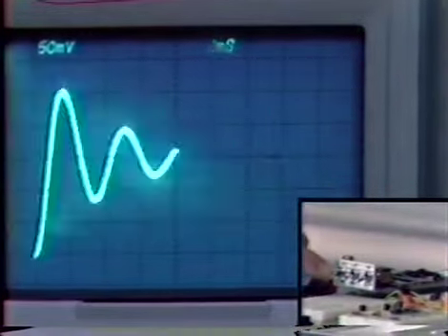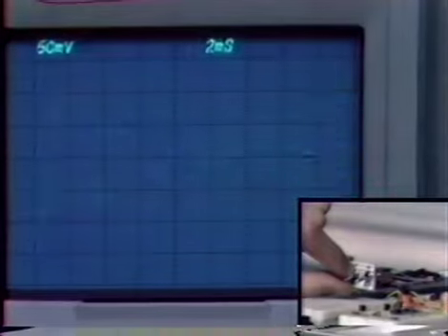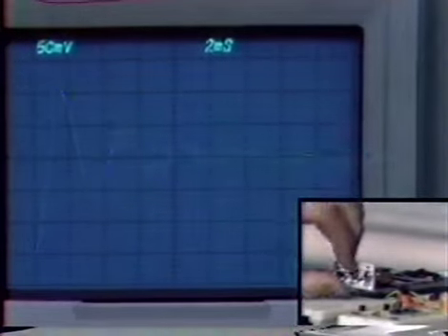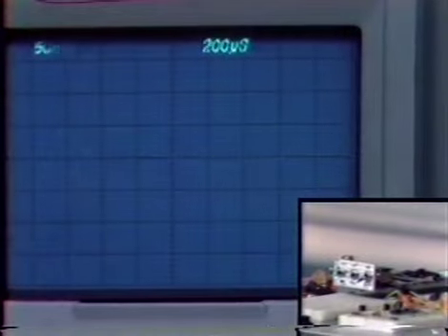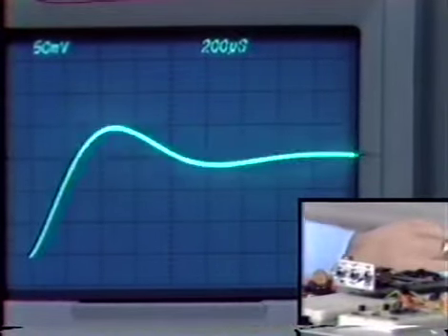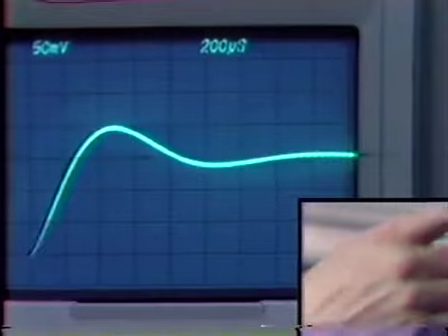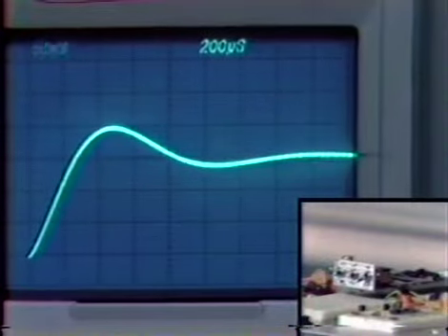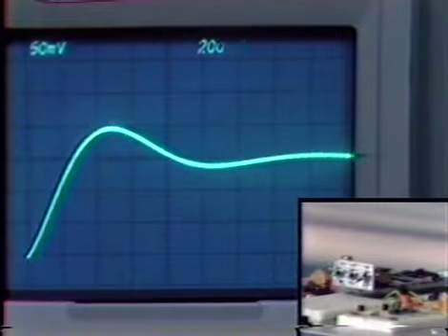But again, at this point, the 1 over S compensation had just completely lost. In fact, we had a lot of trouble with 1 over S compensation when we located the pole at 1 kilohertz. Here the system is very well behaved with this very simple compensating network when the pole is at 1 kilohertz.